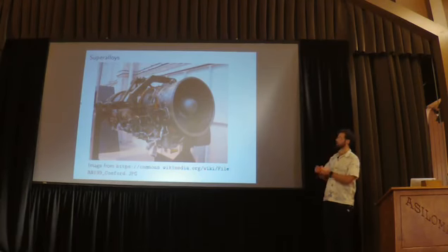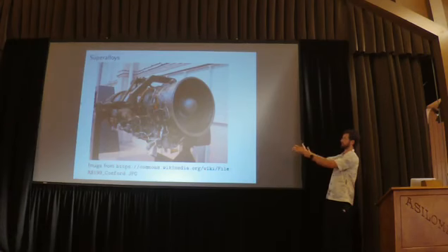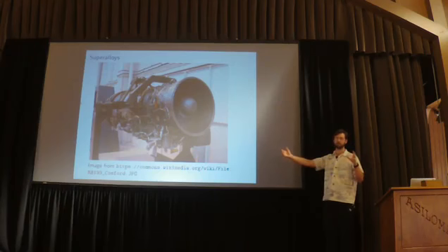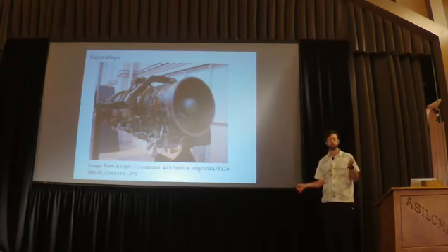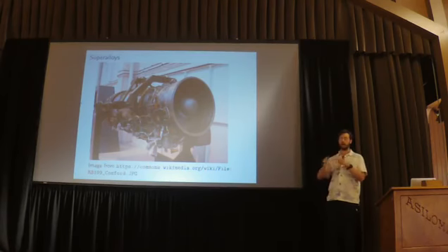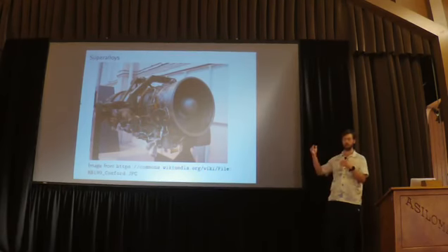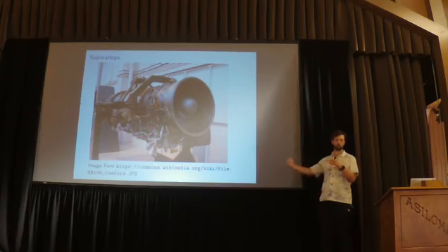Another application for superalloys, more generally, is gas turbines. And this is kind of the jet engine application. These are kind of small gas turbines. Big gas turbines are just used if you have too many liquid dinosaurs and you needed to burn them off for electricity or something. But kind of the game that people play with gas turbines is they want to operate them at higher temperatures. If you operate your turbine at a higher temperature, it's marginally more efficient. And even if these things get slightly more efficient, they burn a lot of fuel. And so if you can get them more efficient, you make a lot of money.